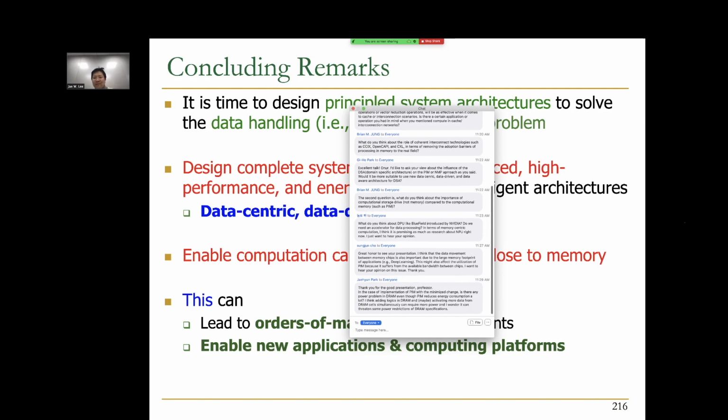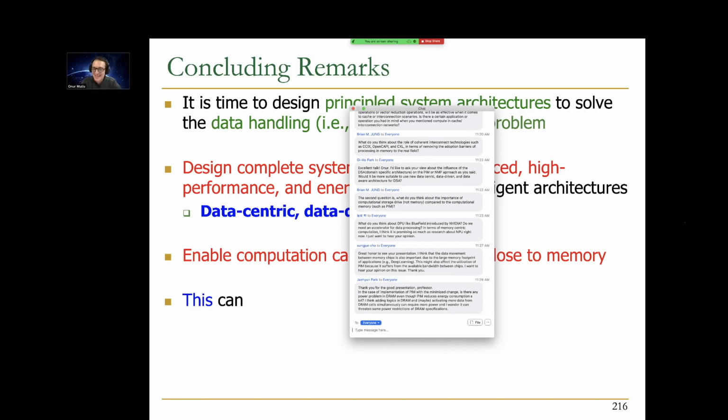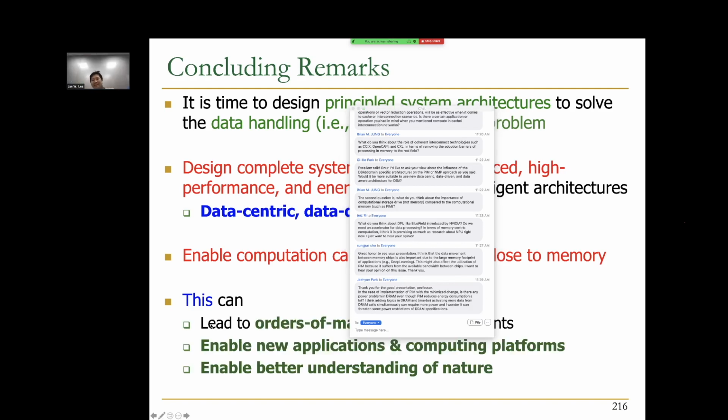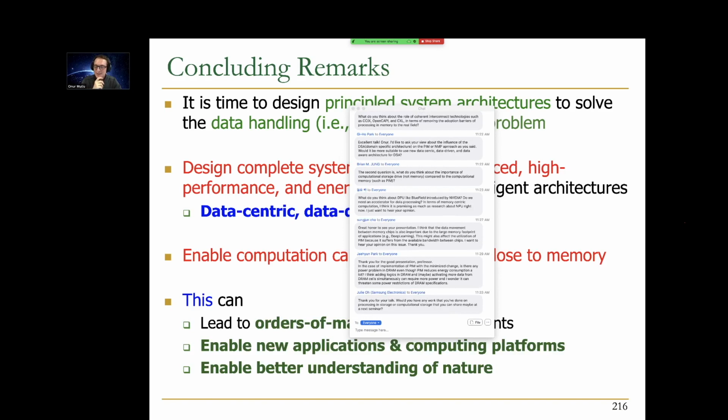Sure. Yeah, that's a great question actually. So I would probably say yes to everything you said. Let me answer the first one. Is it still beneficial? I think the answer is yes, from an energy perspective especially, and maybe from a latency perspective less so. So bandwidth, yes. Bandwidth is part of the benefit of processing near memory in the 3D stacked manner as we discussed. But there are also latency benefits and energy benefits, and I don't think you can get the latency and energy benefits, even if your bandwidth is constant internally versus externally, if you don't do processing inside the logic layer.